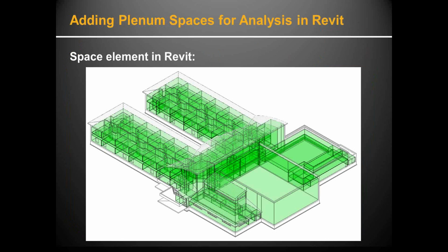It's going to be specific to mechanical, just mechanical load class. There's not a lot of benefit in this for electrical, architecture, plumbing, and a little bit for lighting. Lighting designers might use the spaces. Revit can give you an average lighting level per room, but you don't need the Revit spaces in the plenum.